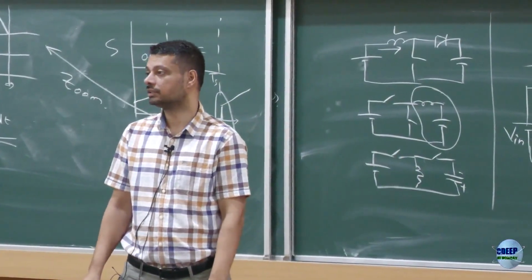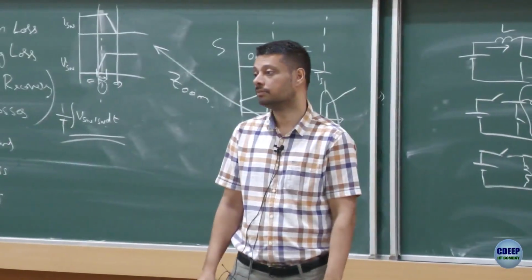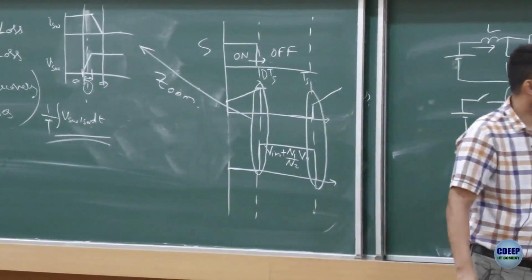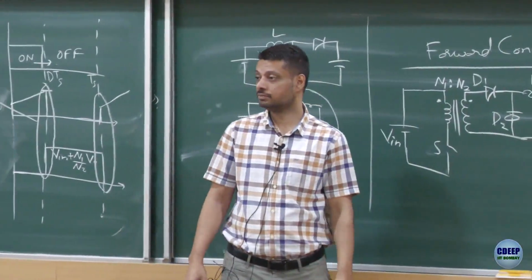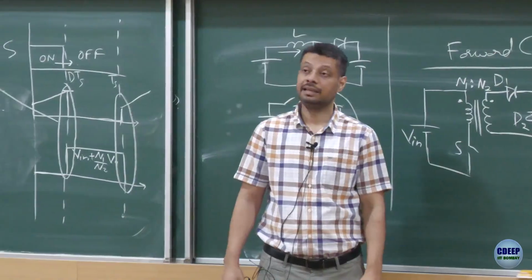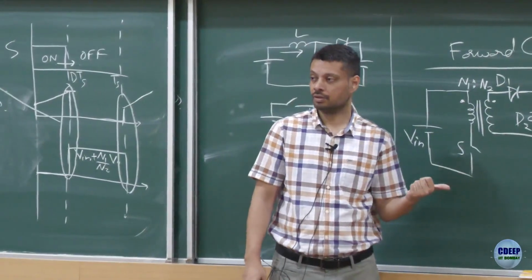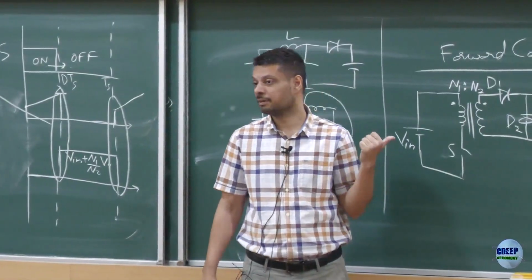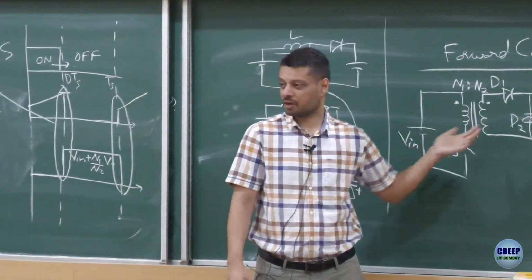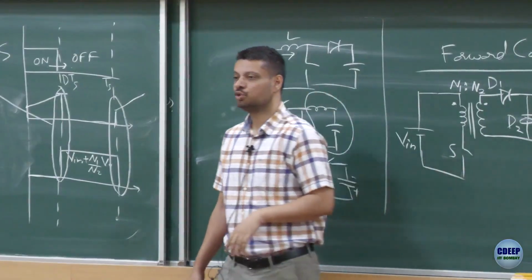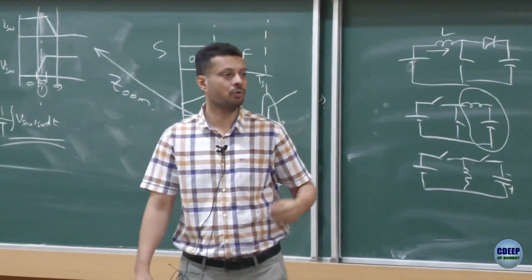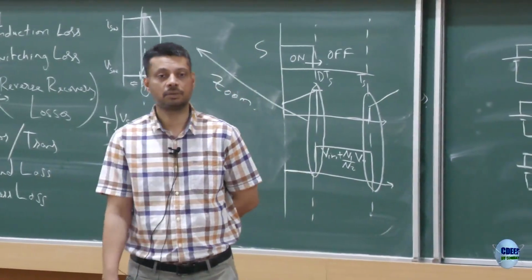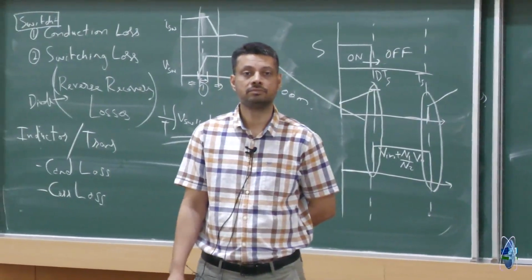So I think, any question? Yeah. What made it better than the buck converter is small output voltage ripple, and in fact better efficiency also. What doesn't make it better than flyback is more number of components, which you may not want if you are building a low power system. Any doubt, any question?